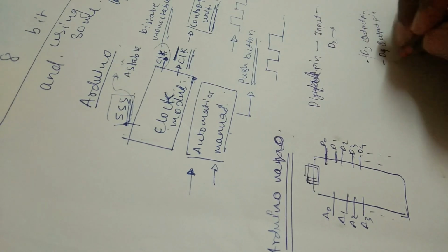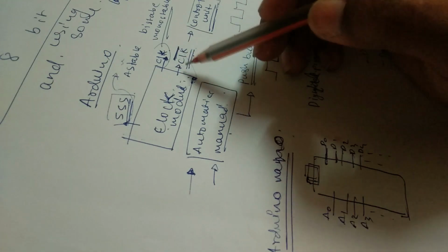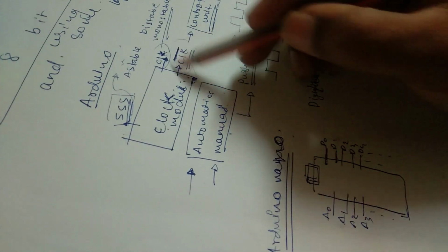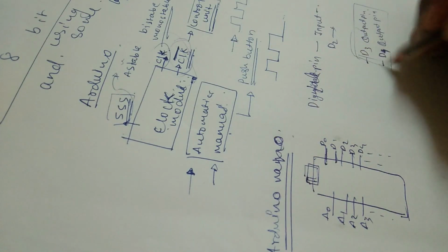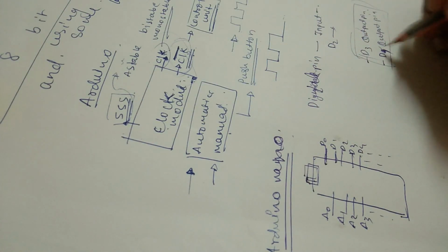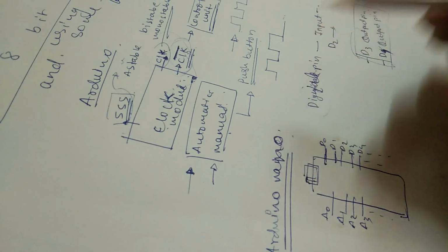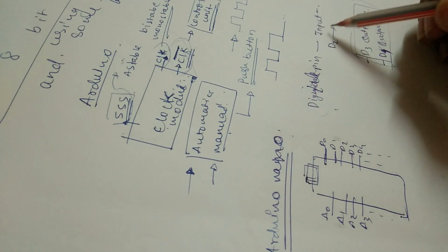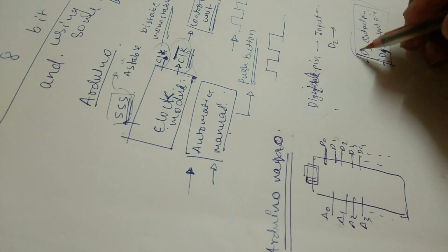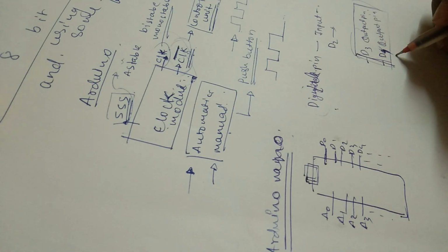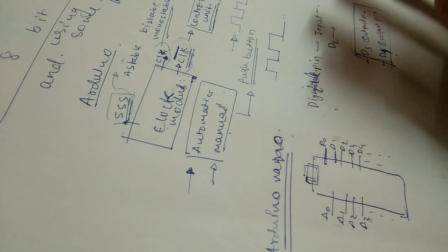Why are these two pins supposed to be output pins? Because as we have discussed here, we need a clock as well as a clock bar signal. So we have set D3 and D4 this way, and when we are programming, we will not be using the digitalWrite function, as it takes more clock cycles and will not make the D3 and D4 pins high and low at the same time. So we'll be using port manipulation here.